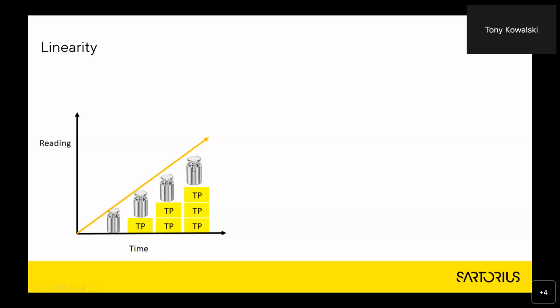So we've only used a single weight, but by taring off, we haven't added together all of the uncertainties of these 3 test weights plus the uncertainty of this weight. We're only ever having one uncertainty of the high quality weight that we're using to test the linearity throughout the range. But as I mentioned, more important for us is the range sensitivity.